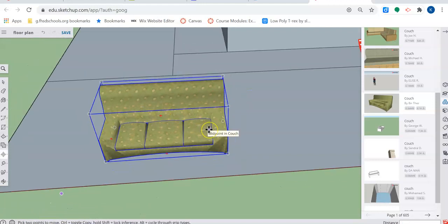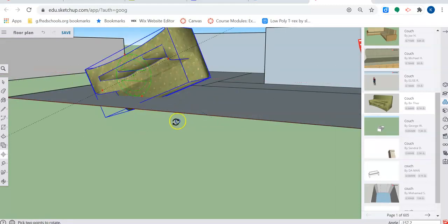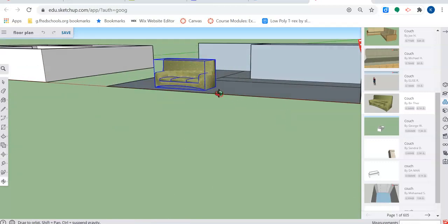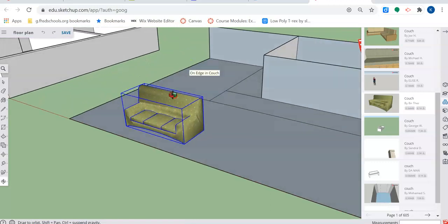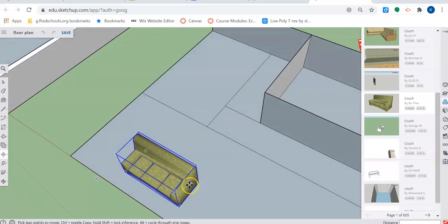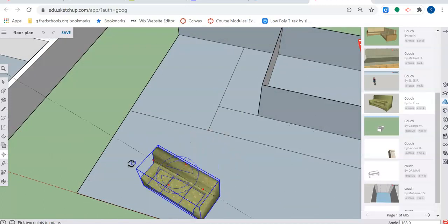You're also going to want to know how to rotate. Right now, I don't know if you can see these little red X's, and I still have the move tool. These little red X's are going to allow you to move and rotate this. So I can rotate this, put my cursor on it, you get a wheel. And again, I'm just using the move tool. You can rotate this from like any side, okay? People get frustrated because they say, how do I turn this around? Right now, I'm in a terrible angle, okay? I can't see the top of my component. So what you have to do is get a good view of the top, and then those X's will show up. If I'm at a bad angle, I can't turn this. So put your X on it, click and drag.